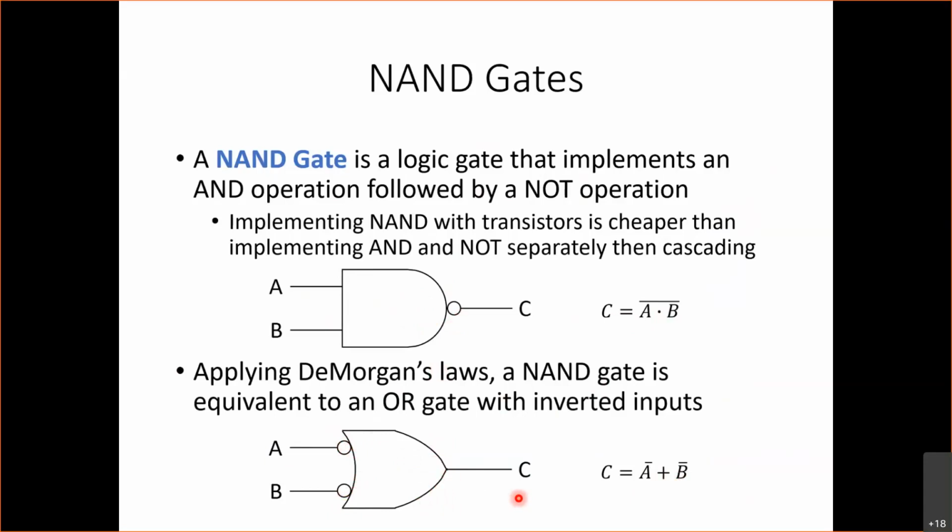The second one doesn't mean that we have a first NOT gate for A, a NOT gate for B, and then the OR gate for both. Right, so logically, it's like having a NOT gate and a NOT gate and then an OR gate. But the first we have only one. Right, but that is logically. But physically, when you actually implement this in hardware, you have just one gate. You have one gate that does all of these operations.